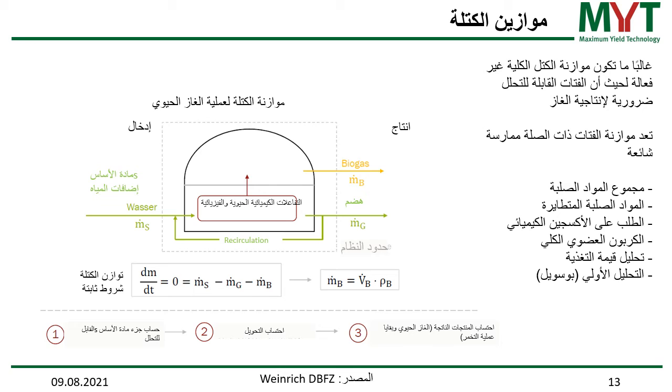And this can be done based on the total solids. More often on waste or agricultural products, it is done on volatile solids. Within the wastewater sector, usually chemical oxygen demand is more the basis. Science and also modern wastewater treatment facilities go after the total organic carbon, TOC.